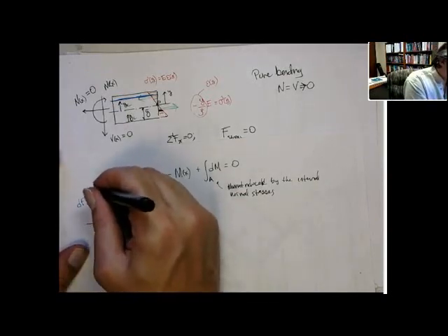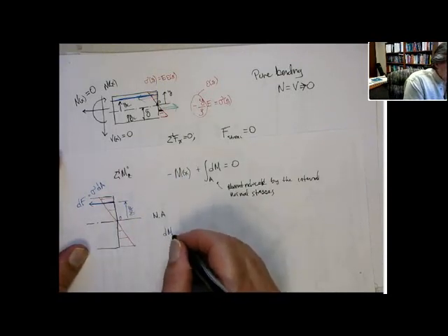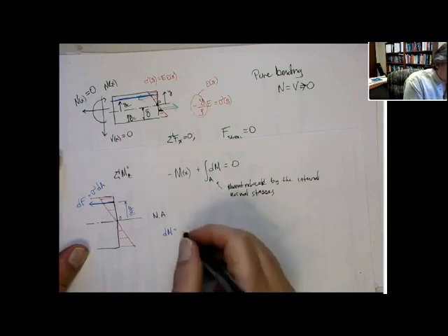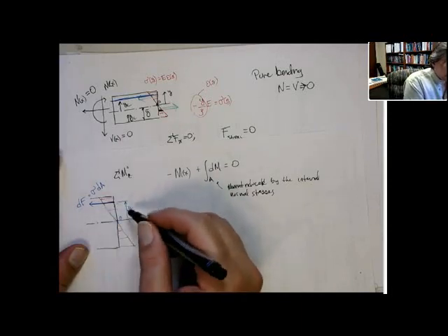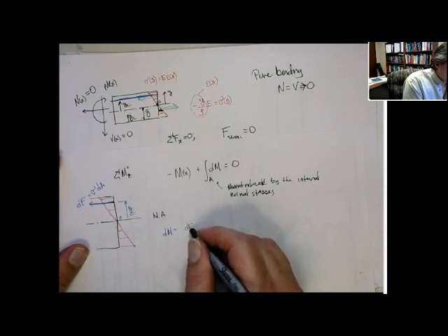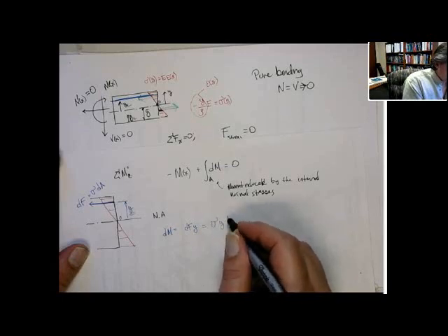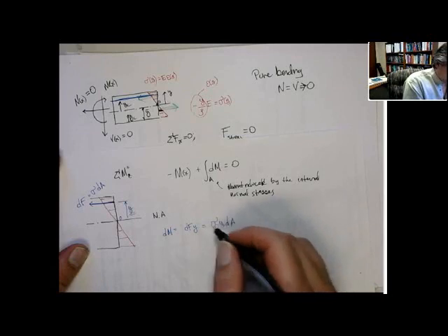So that equals the normal stress times the differential area, correct? That's the force, stress times area. The differential force is the stress times the differential area. Now this produces a moment around point O, and its moment arm is y. So the differential moment is positive, right? This way. That's a positive moment. The differential moment is the differential force times y, and here we get sigma y. Now if I take that and put it into here,